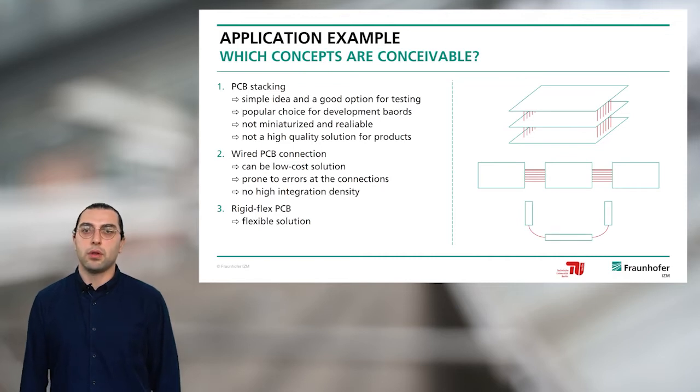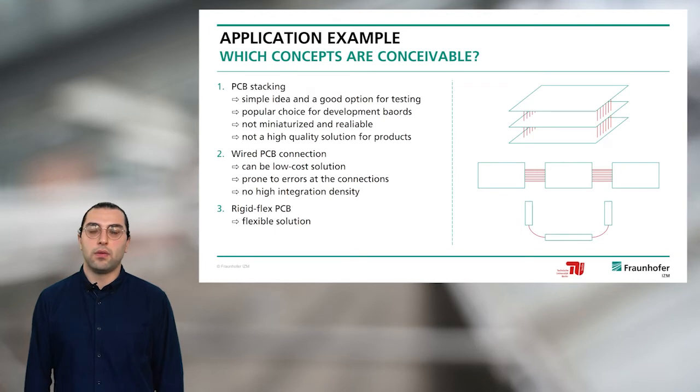The first option would be to make a PCB stacking. It's easy to realize by using headers in the PCBs and connecting them with each other. And it's a good option for testing and for development boards. But it's far away from being a miniaturized device and far away from being a reliable and high-quality solution.